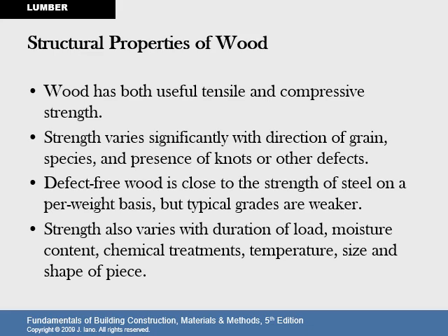A quick note about those wood knots. They're very difficult to work with. Sometimes if the saw blade takes them, it might send a bump or send things in a different direction. Unintended consequences. The presence of knots is always something to be avoided if possible. Also, with time, you may lose the inside of the knot, creating a hole.